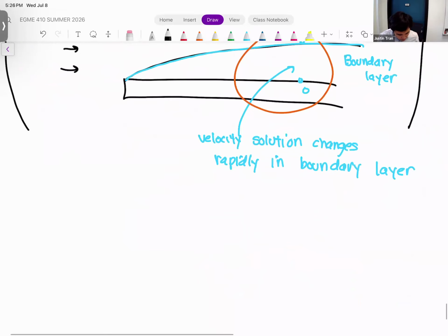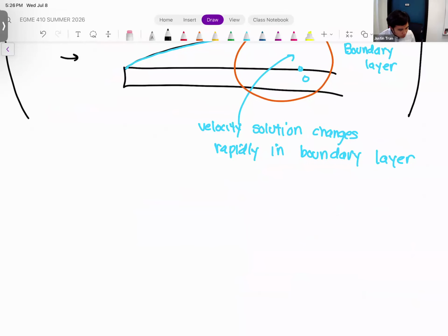One other thing that you can check, and I also check this for the project in this class and for my students as well, is that your solutions or contours for things like deformation and stretch should be very smooth.